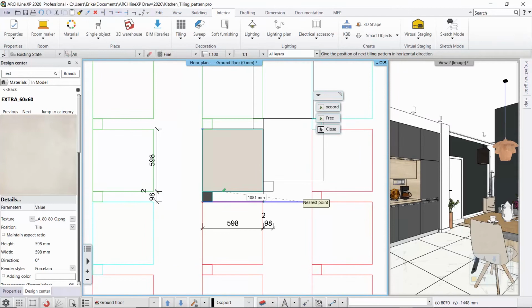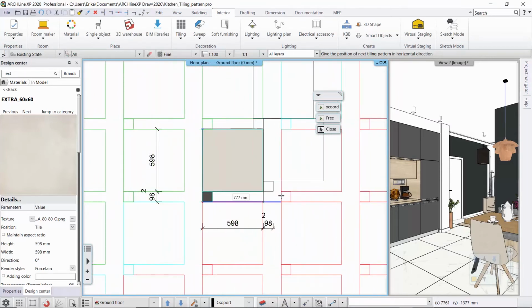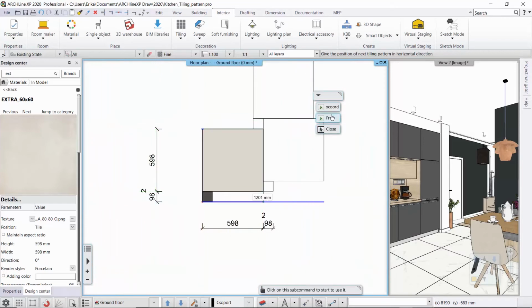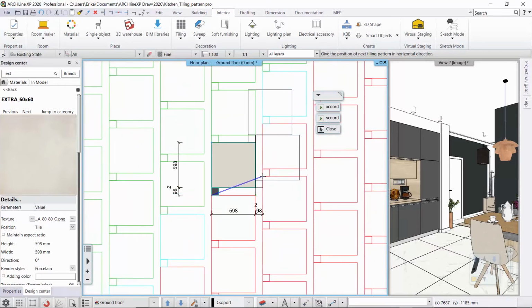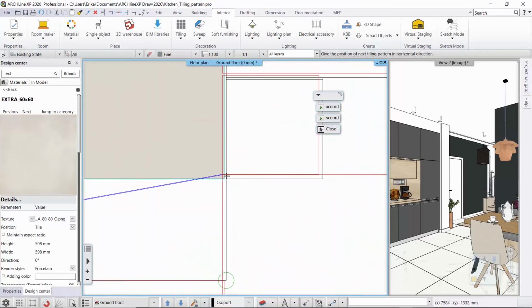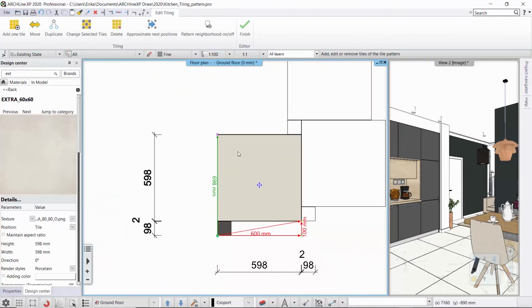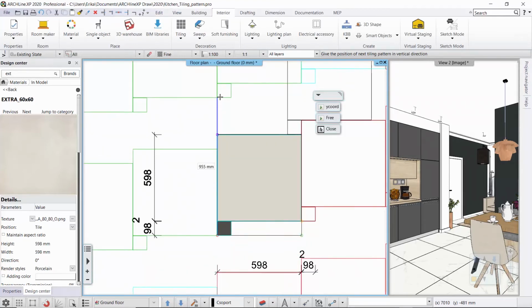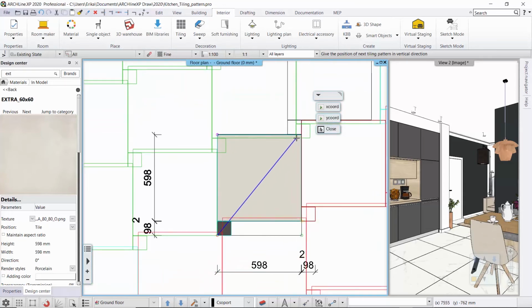By clicking on the dimension line at the bottom of the enclosing rectangle, you have the option to enter this graphically. So you can move the sample in the XY direction. The cursor will show the pattern that you need. If there is an offset in both directions, select the free option, and now let's see that I can place the pattern very nicely on the next point so that the exact location of the pattern can be given. The arrows also show the offset.